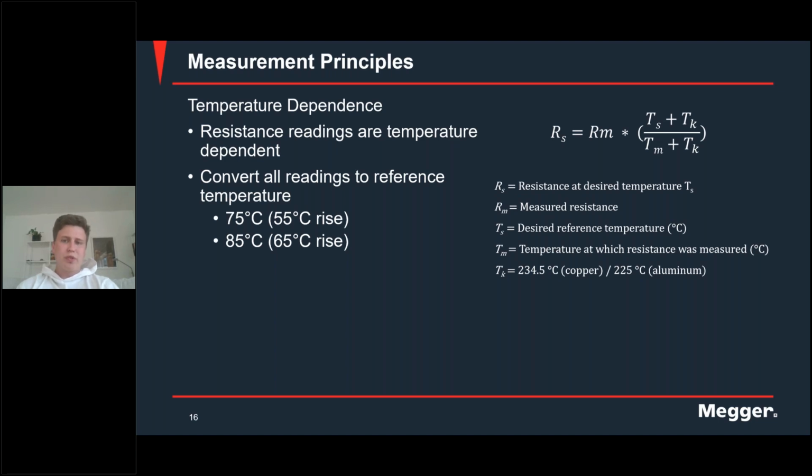But for larger power transformers, you sometimes have three OLTCs, one for each phase, and then it might not be as critical to have it close to the neutral. So it will vary where you are, but mainly where you have the neutral point. Yes, thank you.